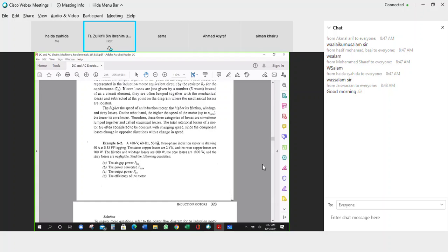So this shows you the machine operates at the rated condition. When we calculate here, we get 50 HP. It's the same. Therefore, the induction motor efficiency is straightforward: power out divided by power in, times 100.